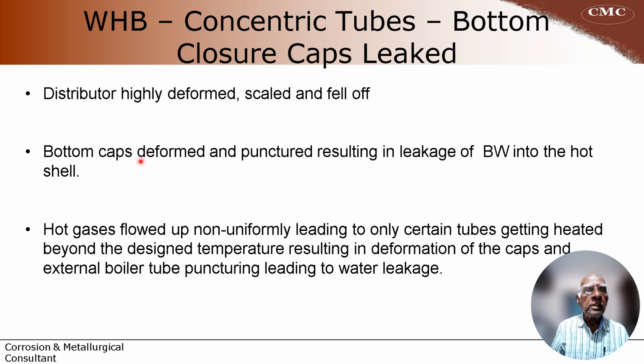The bottom caps in that portion deformed and punctured, resulting in leakage of boiler water inside the hot shell. The hot gases flowed up non-uniformly, leading to only certain tubes getting heated up beyond the design temperature, resulting in deformation of the caps and external boiler tube puncturing, leading to water leakage. There is an external boiler tube that got punctured.